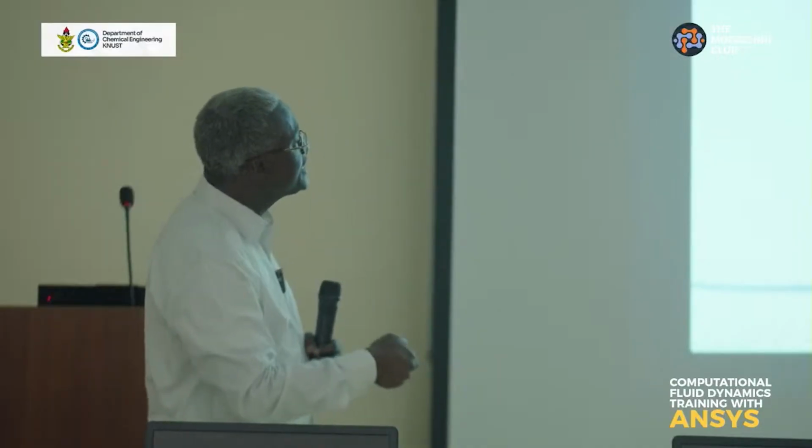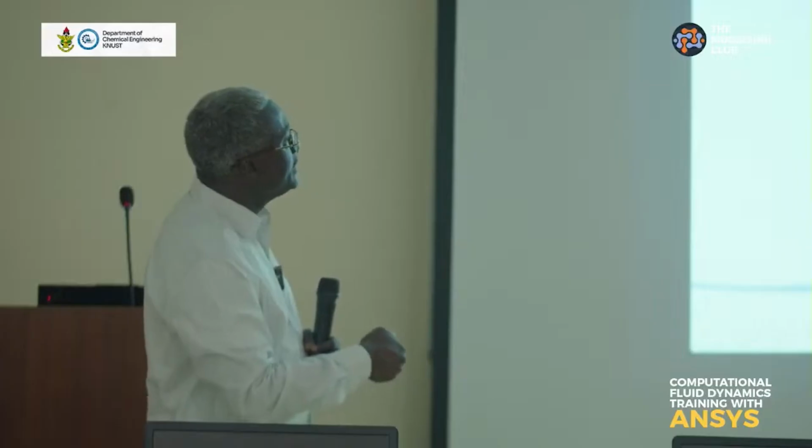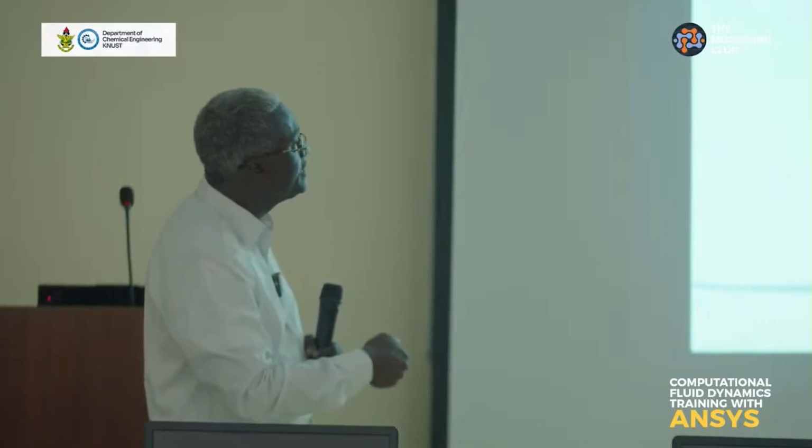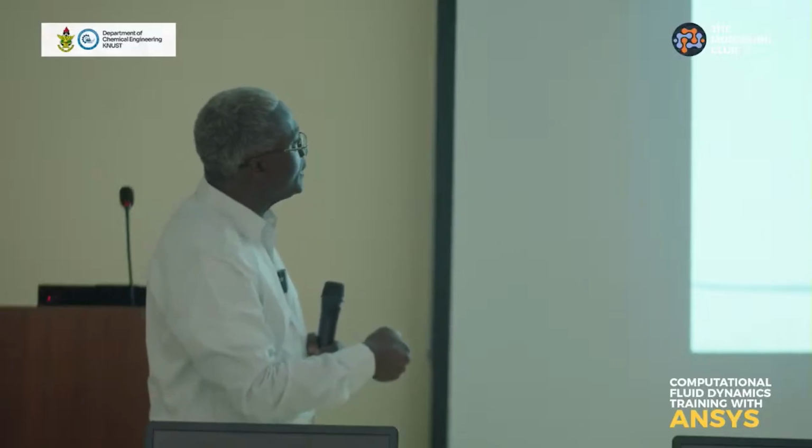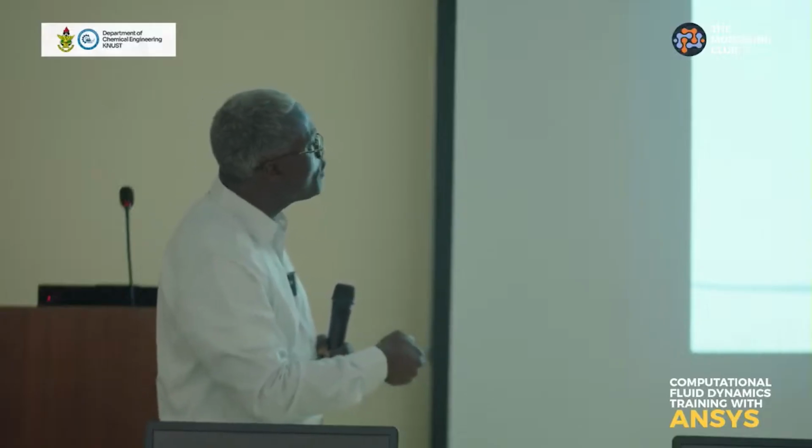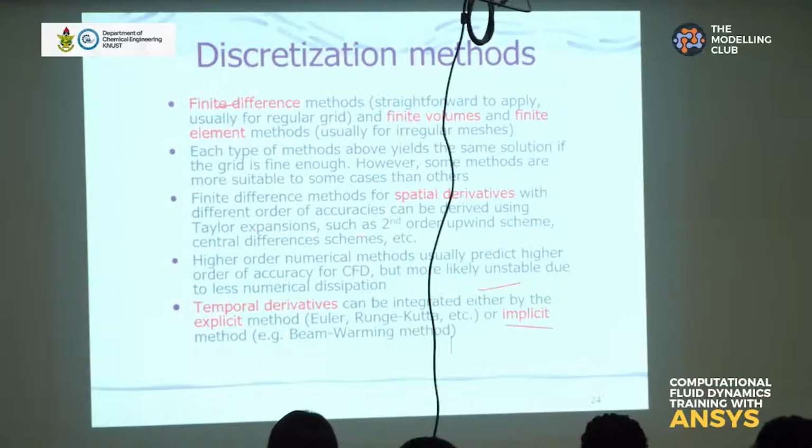But suffice it to say that the simulation will be accurate depending on your order of differentiation, such as whether you are using a second order upwind scheme, central differences, and so forth for the finite difference methods.